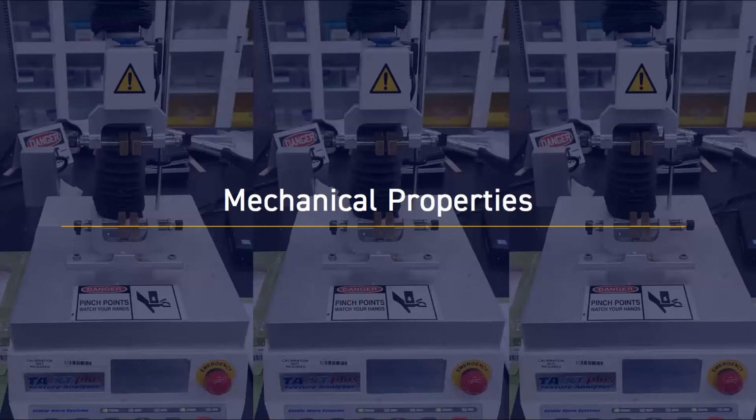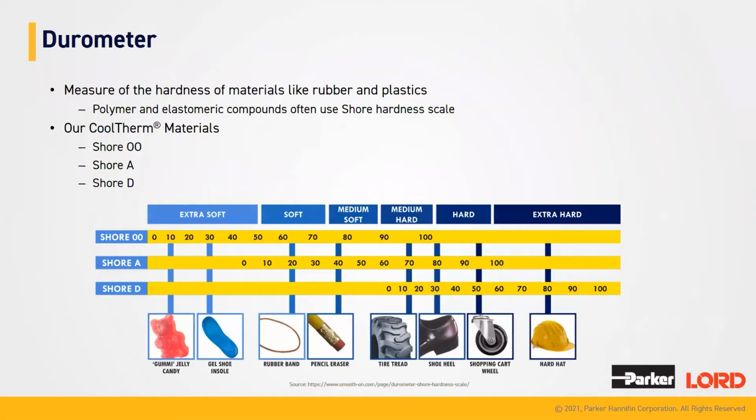So moving on to mechanical properties. One of the most common mechanical properties that we are asked about is the hardness. It's also known as the durometer. So when you hear us reference the durometer, it is a measurement of the hardness of a material such as rubber or plastic. Now, when it comes to polymers and elastomeric compounds, we typically use the Shore hardness scale.